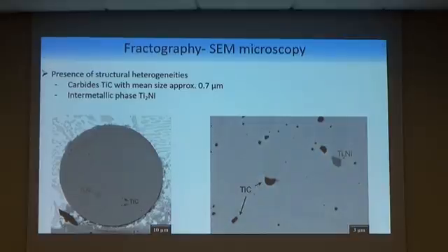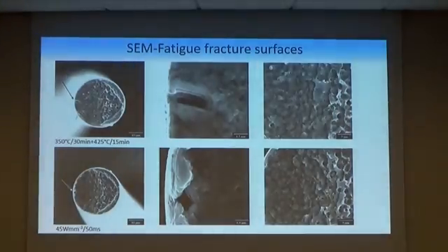It is important to mention that this is a combination of a superelastic matrix and non-transforming impurities. So probably higher transformation stresses produce higher incompatibility between matrix and inclusions, which causes higher stress concentration in these particles.